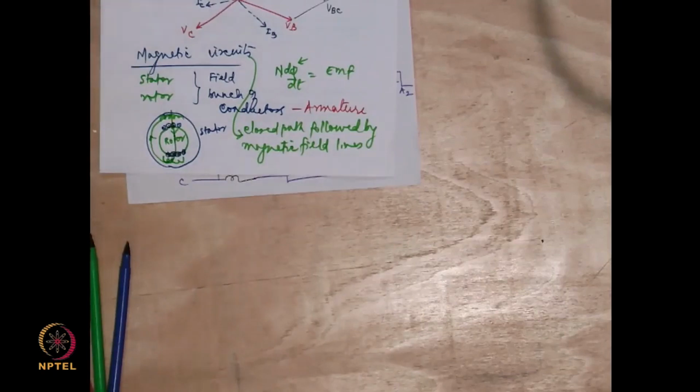That means I have to forcefully push it through the air gap, which means I will require more current to produce a higher strength of the magnetic field as compared to what I would require in the case of a transformer. In the transformer, there is no air gap, because of which I don't have to do this tough job of pushing the magnetic field lines through the air gap. Whereas in the case of an electrical rotating machine, I had to push it through the air gap, which means I will require more strength of the current, generally.